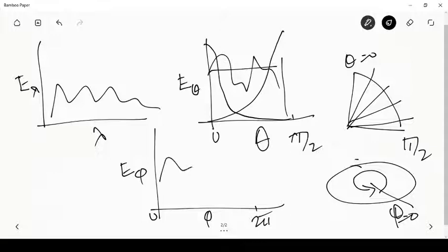This can also have a certain kind of variation, right? So whenever we define radiation, the most fundamental quantity that defines it should be the energy emitted per unit area in a particular wavelength, in a particular theta and phi, right? So directional spectral emission per unit area is going to be the most fundamental quantity of radiation emission.